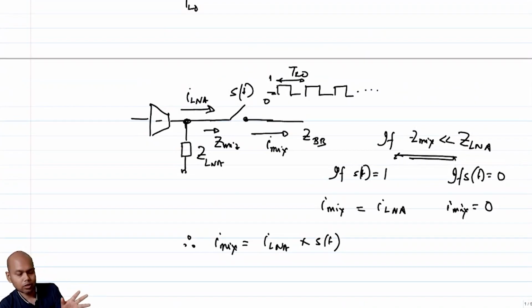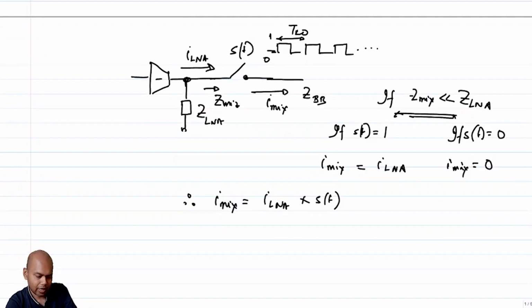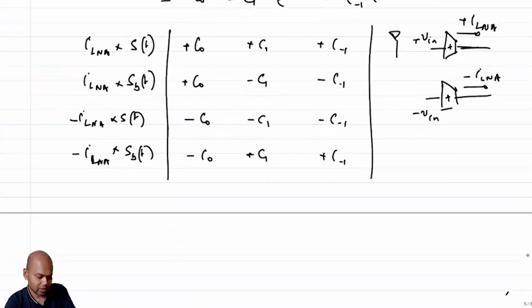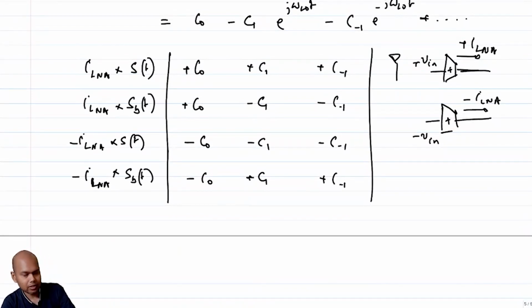It's essentially a current source which is pushing a current into the switch. So if you have another copy of it which also pushes a current into a switch, then I simply add up those wires. Then the summation of the current through the wires is basically the current that is coming through each of these two paths added up, right? So that's the whole idea. The summing is much easier in currents, right? If you have to subtract, then you have to first flip and then sum.